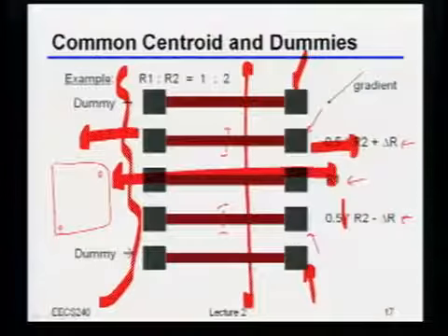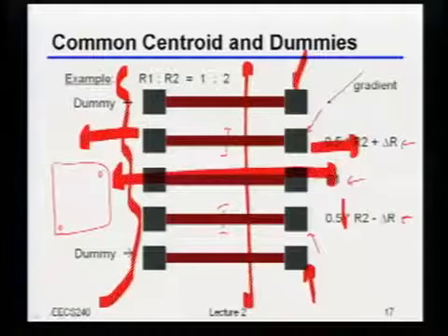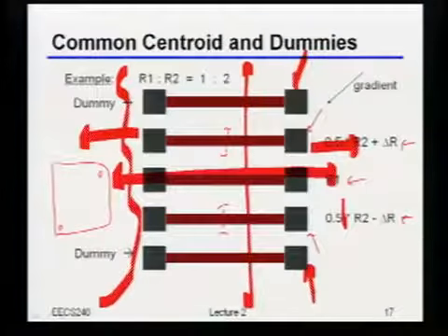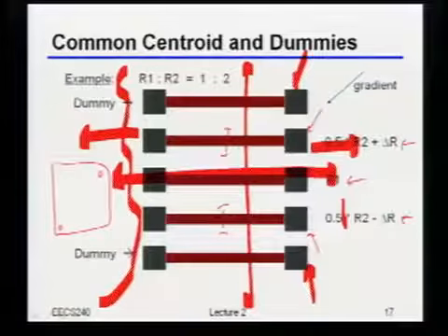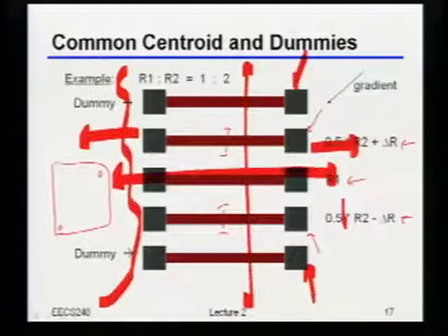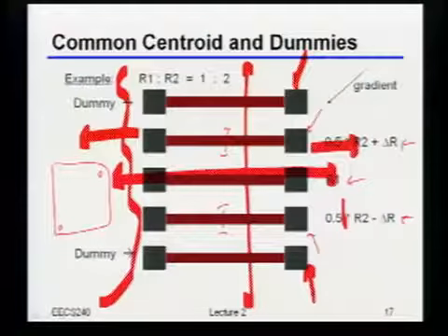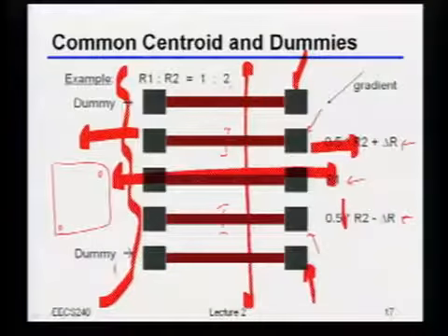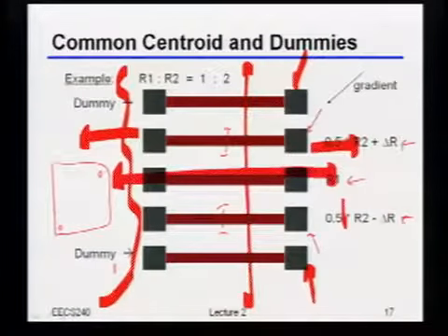Because if you make it the same, then just about no matter what they're doing, you should actually get the right answer. Now, to be fair, you do want to know a little bit about what it is they really do, because obviously if you take this to the extreme, then all you can do in your entire chip is have this thing and then dummies all around it. And that's obviously not particularly useful. So the spatial extent of things is important, but certainly in the local environment, meaning within, let's say, 10, 15 microns or so, you want to keep that basically the same.